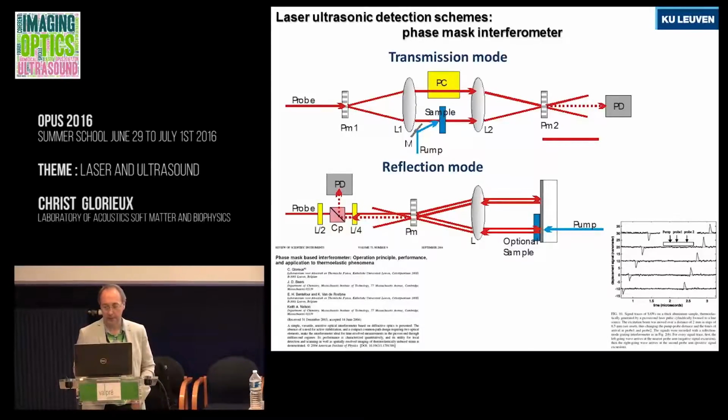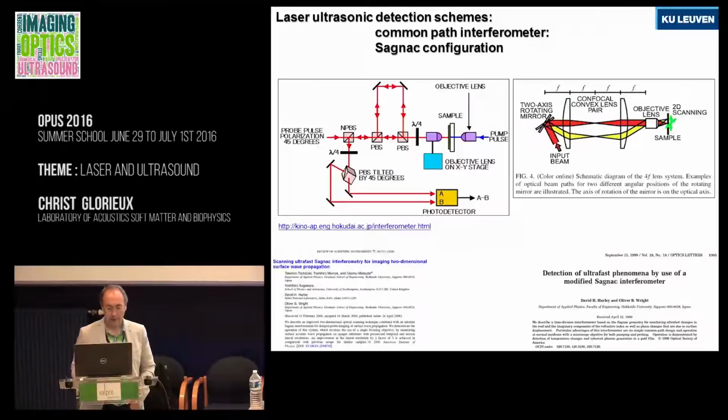You are looking at the difference in displacement in optical path between this point and that point, and you can use it for detecting waves. For example, if you detect a wave in the middle, well, maybe not exactly in the middle, it will first arrive at detection location 1, and a bit later it will arrive at detection location 2. So you see the wave two times, once negative and once positive, because once it's pushing forward probe beam number 1, and the other time it's pushing forward probe beam number 2. So again, very simple interferometer. And in principle, it can work for everything.